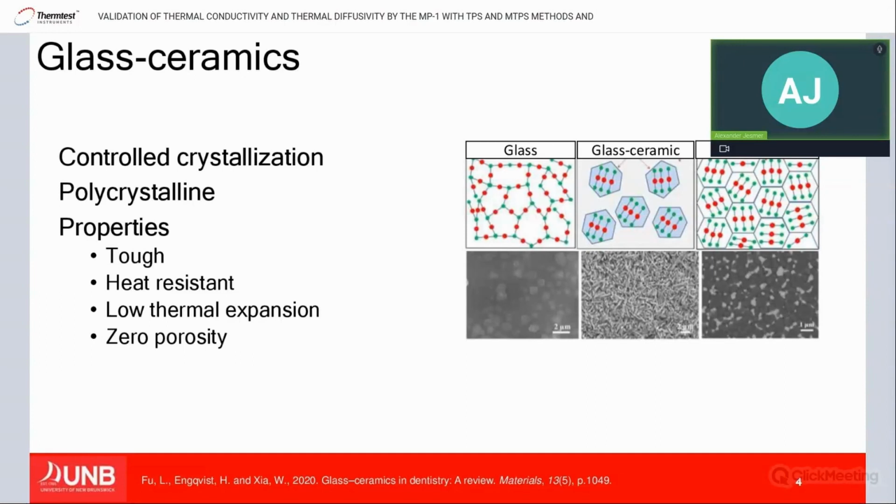So these polycrystalline phases have different sizes and different quantities within the material. And that's what determines the overall properties of the glass ceramic itself. So you have anywhere between 0.5% and 99.5% essentially ceramic content as these small islands within the amorphous glass, as shown over on the right side in the little diagram. So starting at an amorphous glass, then you go all the way on the other end of the spectrum, you have a ceramic, which is close packed crystals.